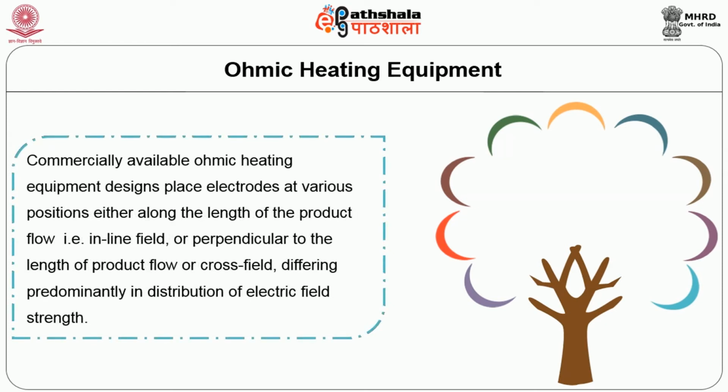Commercially available ohmic heating equipment design place electrode at various positions either along the length of product flow, that is inline field, or perpendicular to the length of product flow or cross field, differing predominantly in distribution of electric field strength.